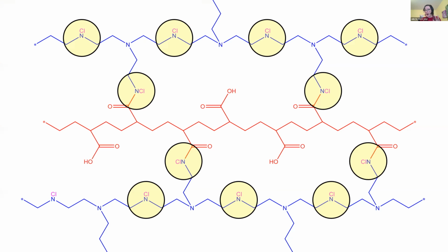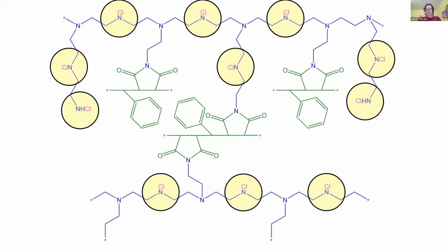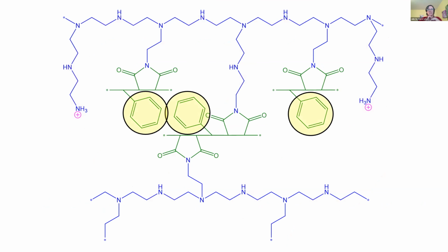We still wanted to design a polymeric coating that could inactivate microorganisms that contact it, but we also wanted to introduce a functionality to try to inhibit the initial microbial adhesion and facilitate the removal of bacterial biofilms that do adhere, sort of a non-fouling or easy clean surface. So to do that, we changed one component of the chemistry, and that's shown in these highlighted styrene subunits, to help reduce the surface energy so that the coating would also be non-fouling.